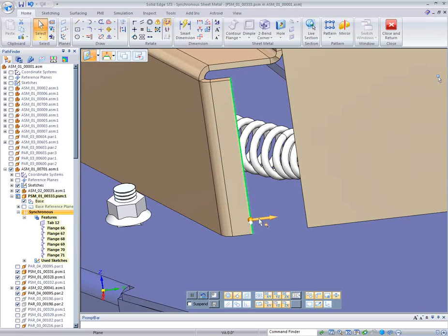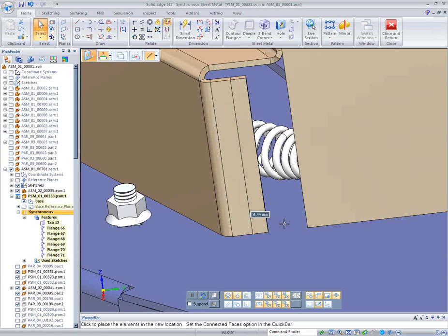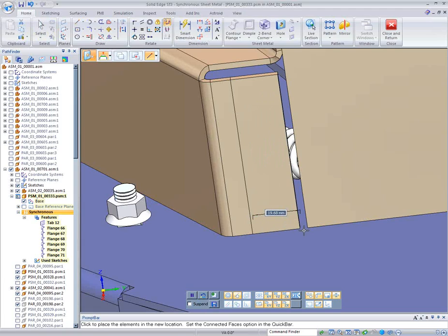I'm going to hold down the Shift button and grab the primary axis of my steering wheel. And as I do, Solid Edge instantly is looking for an input, so I'm going to have that handle move 1 millimeter out from that face. So as I grab this and start to move, my handle is now 1 millimeter off of the face, almost like moving 2D. I want to move something from here to here. Where do you want it to start? You can move it right in the center, or off to the side, or wherever you like. That's where I want it to start from.